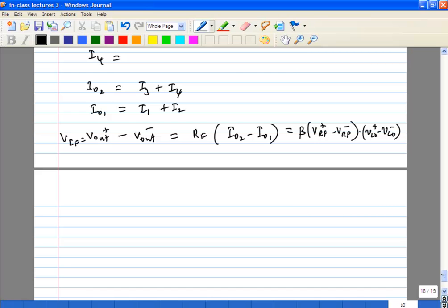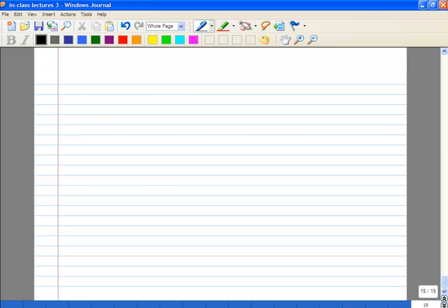We wanted to get a product of the RF and the LO terms. Okay. So you can get extremely high IIP3s. Okay, somewhere around like 40 dBm, which is really good, right? Because the IIP3s we have been looking at are maybe like 10 dBm, 20 dBm, something like that. 40 dBm is quite good. Okay, but if you look at the noise figure of this guy, it's actually very high.